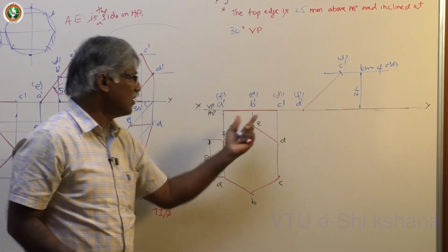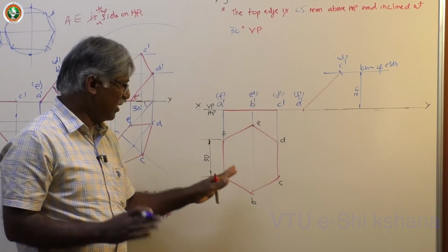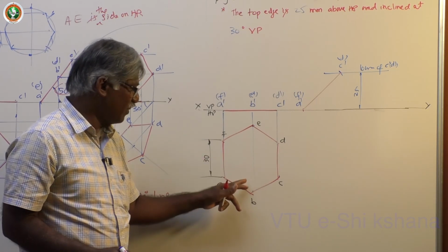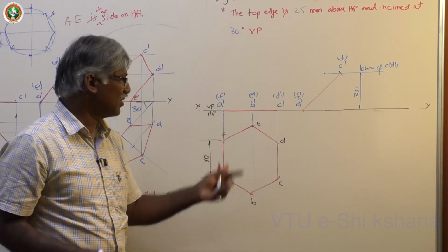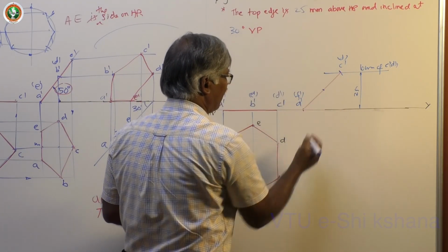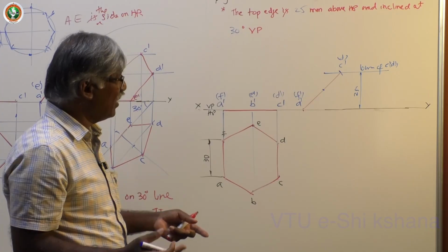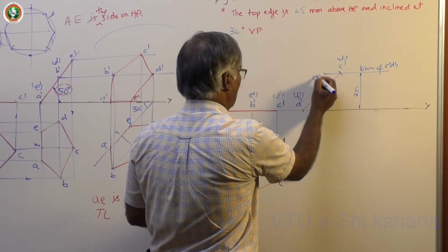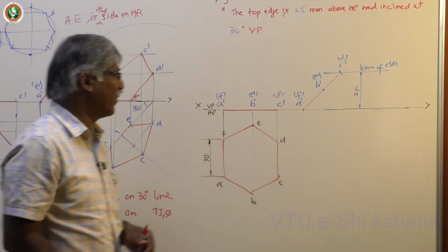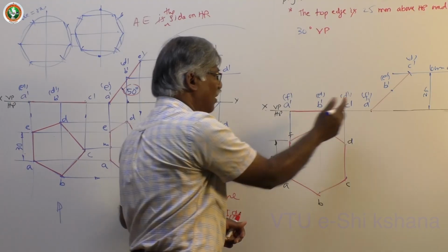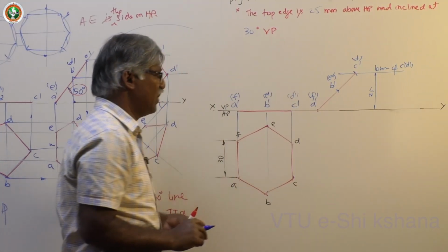Then how to fix this? It's very easy. A characteristic feature of hexagon, square, etc., is this type of edge condition, corner condition. You get exactly half, the midpoint. You need not note it down. Simply mark P dash, E dash. Otherwise you can have a line also for your reference. No problem. But manually you should do it. Take this arc and draw it. Even though it is the midpoint, you can do it.